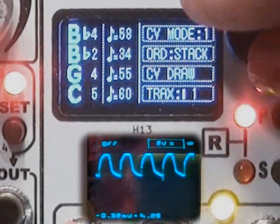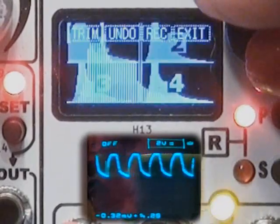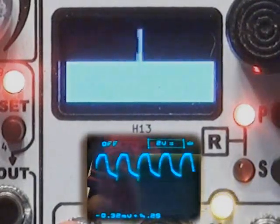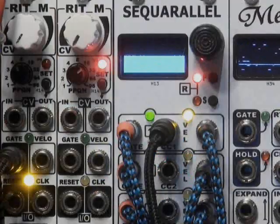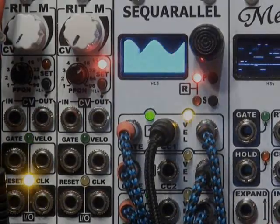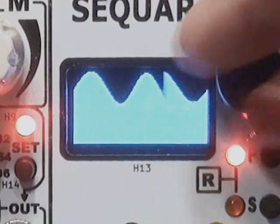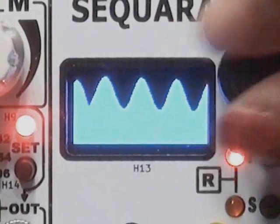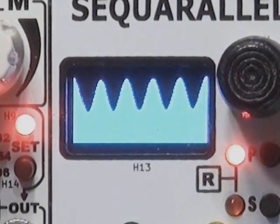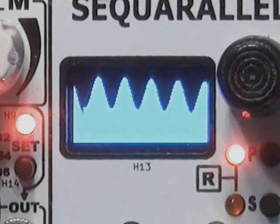The next type of envelope is CV draw. This records whatever is coming into the CC5 jack, then captures it as an envelope. I have a CC5 patched to a RITEM's gate output, so it's 0 to about 4.5 volts, purely pulses. Now over to a multiplexed LFO. The recording scan rate can be slowed by scrolling right, clockwise, or sped up by scrolling left. The LFO is dual, so one is offsetting the other, which is why the sine waves are moving down slowly. The last full-width screen completion is captured, which helps to grab the one you want when the sample rate is slower.